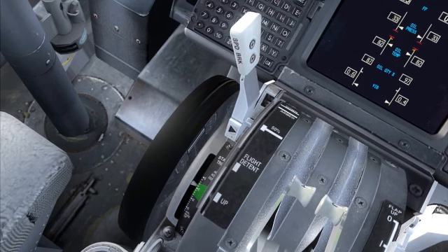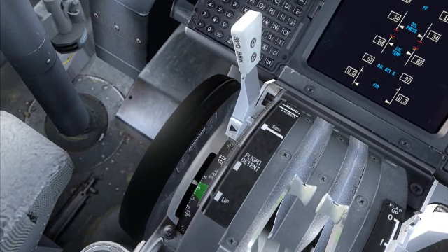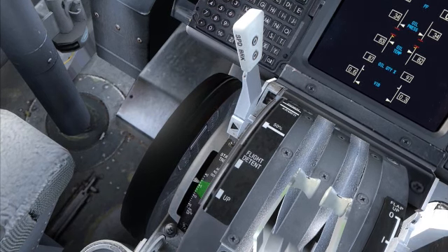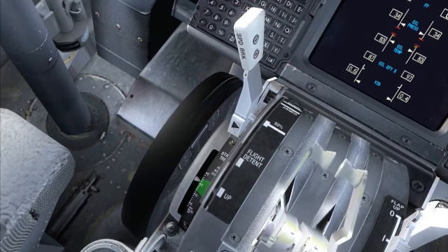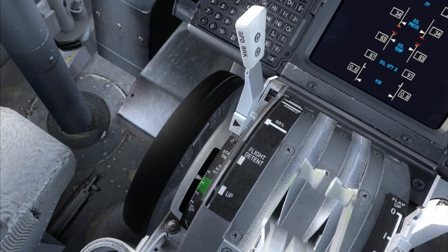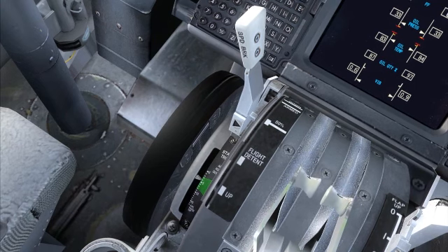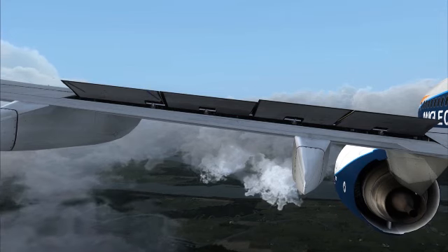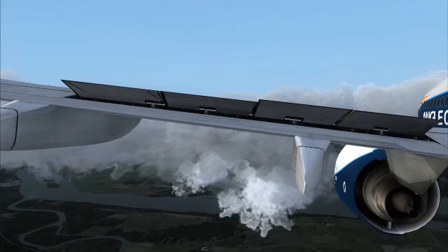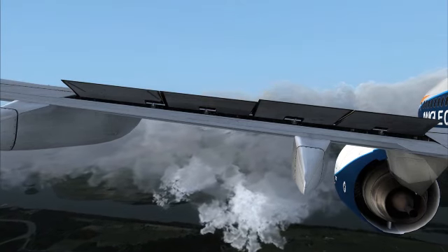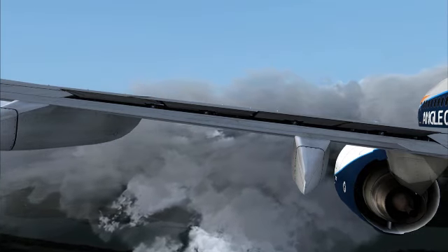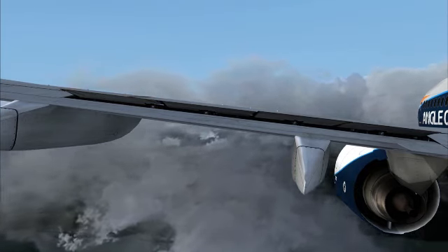Manual override of this feature is also available, meaning pilots may bypass this load alleviation mechanism in case it becomes imperative for safety reasons. They do this by manually moving the speed brake lever from the 50% of flight detent position into any other position between the flight detent and up. The lever will return to the 50% of flight detent position if pilot input is stopped, provided load alleviation is still active. When load alleviation becomes inactive, the pilots may operate the speed brake lever manually and under normal operation.